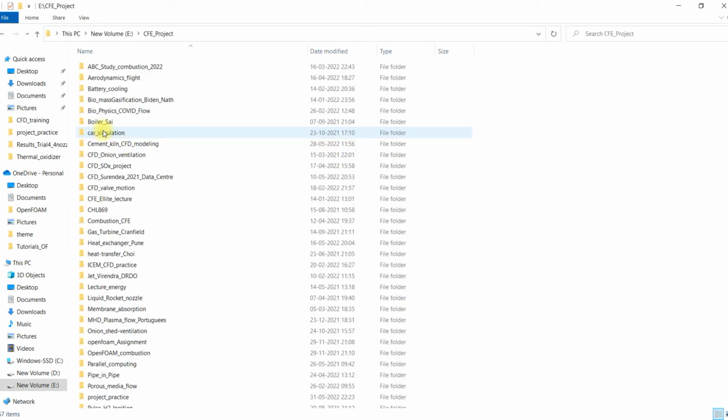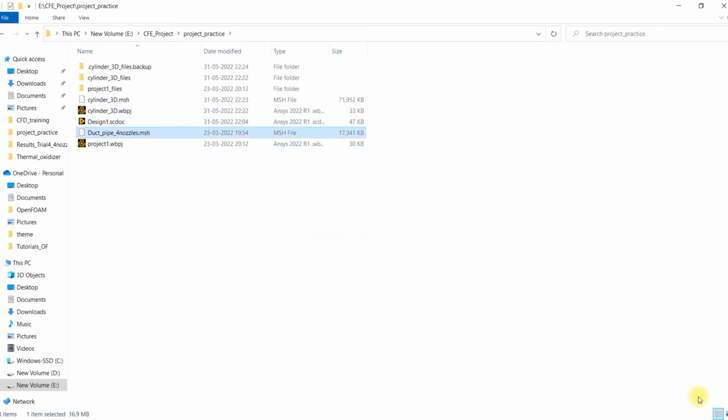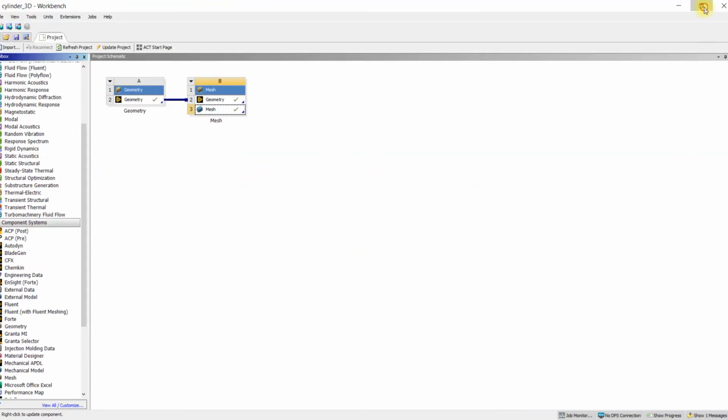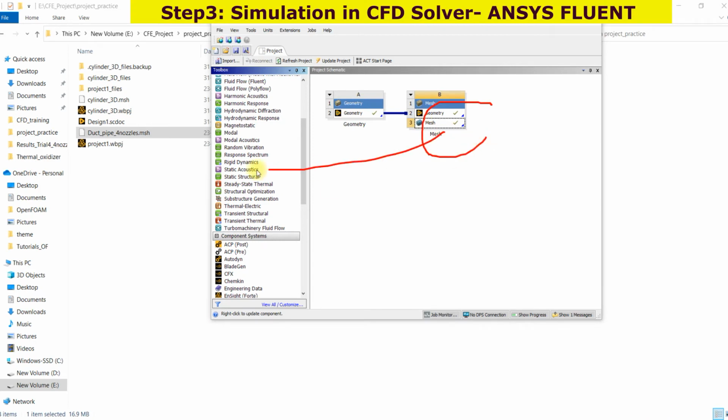And after that, open in the Fluent option. Open the Fluent window. You have to open it using ANSYS Fluent simulation. The first step, geometry making, and meshing are okay. Then the third step is to create the Fluent. After selecting it, open the Fluent window, and please copy the path of the file.